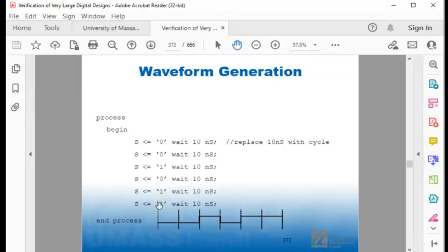This is a way to generate stimulus. It's a very brute force way, right? Generally, you don't want to have something that you put in every clock cycle. I also use the wait statements in this, but it'll generate this. It is more likely that you put some kind of record in and you would iteratively read from the record. Doing something like this is difficult when you have more than one signal, right? And obviously, we have systems that have many more than one signal.